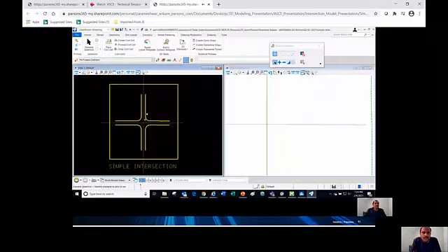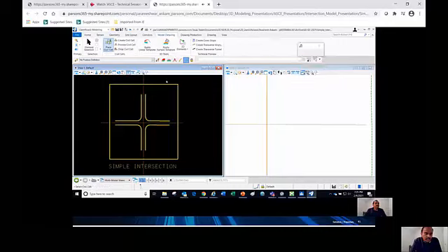Yeah, in this video, I'm going to present how this simple intersection civil cell works. There are two cross streets here with alignment, and the civil cell that I'm going to put is the simple intersection. I just picked two cross street alignments, highlighted those two alignments, and then it's going to produce a 3D model of that intersection.